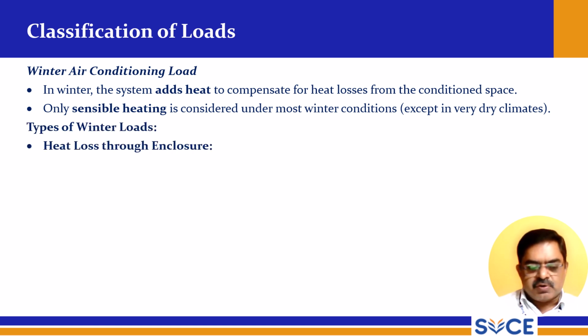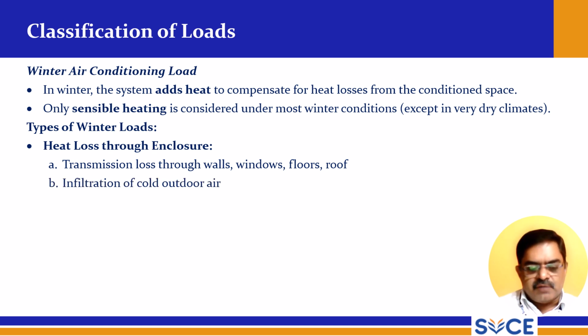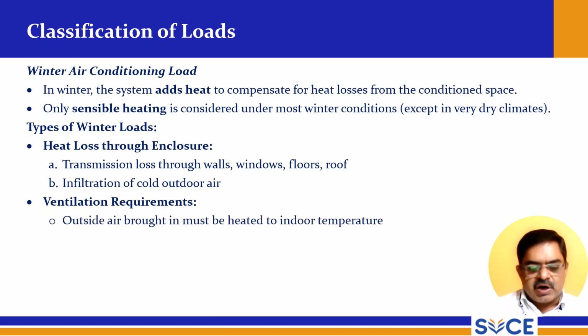The types of winter loads are the heat loss through the enclosure, and transmission loss through walls, windows, floors and roof, infiltration of cold outdoor air, and ventilation requirements. Outside air brought in must be heated to indoor temperature. There is also desired humidification if the relative humidity is low.